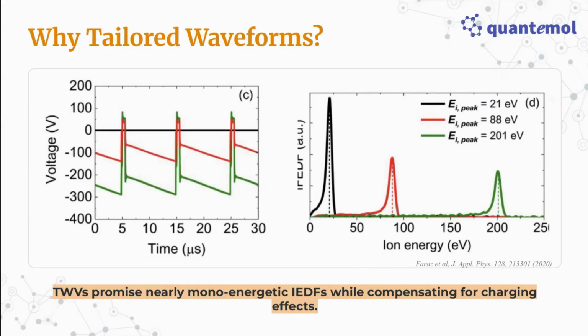Now, one thing you have to consider is that electrons only reach the surface during the short positive phase. So over the long negative phase, only ions reach the surface. So they still get some transient charging during this negative phase, which is why you introduce this slope in the negative phase to counter the charging of the wafer, but also of the blocking capacitor in your network.